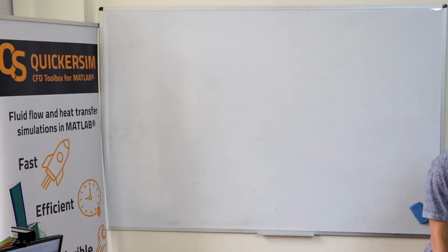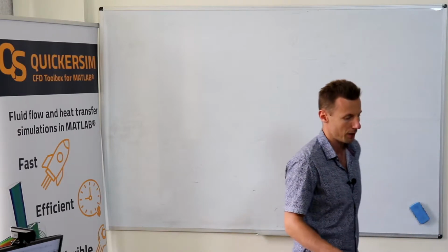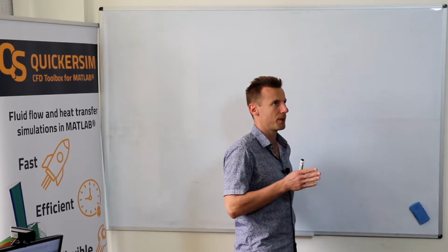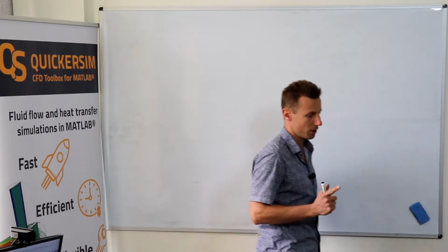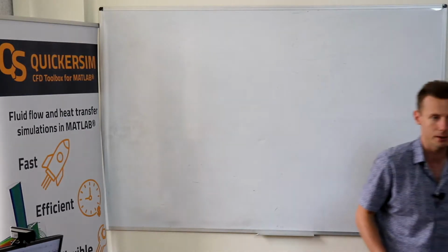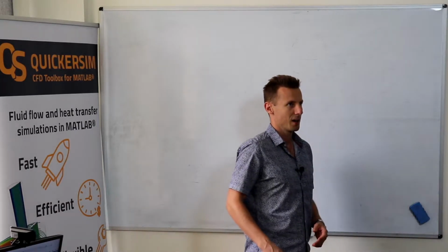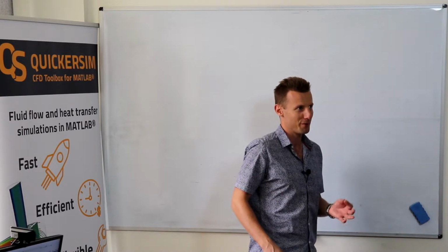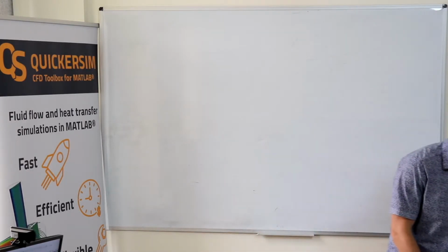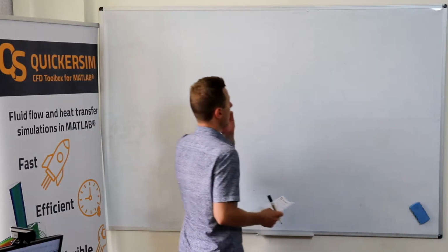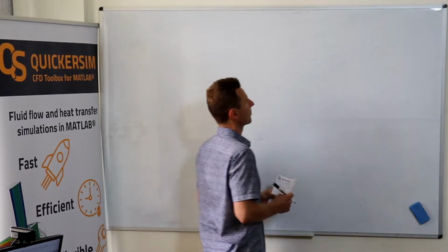And this comes down to the fact of how to properly choose location of storing the variables, the pressures and the velocities, which is extremely important, because otherwise you will run into a numerical scheme that is unconditionally unstable, or at least very, very often unstable. And let me show you the following problem.